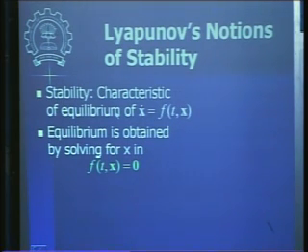You introduce one more state, x dot equal to, say, y, and transform it into this kind of form, so that you can represent that system as a first order nonlinear differential equation. This is possible for all the robotic manipulator systems; they can be put in this form.